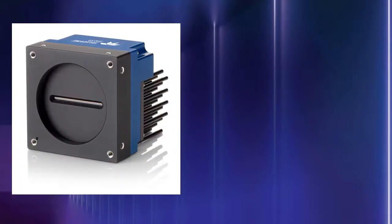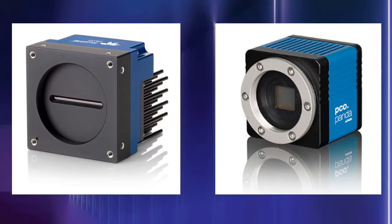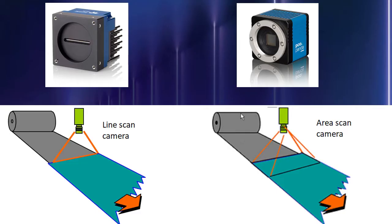Both Linescan and Areascan cameras are used for inspection. They are similar in basic operation, but there are some important differences that make one or the other a more desirable solution depending on the application. A typical Linescan camera system is faster with higher resolution than its Areascan counterpart. It images only one video line at a time versus the two-dimensional area camera. Cost and complexity, however, are the trade-offs.